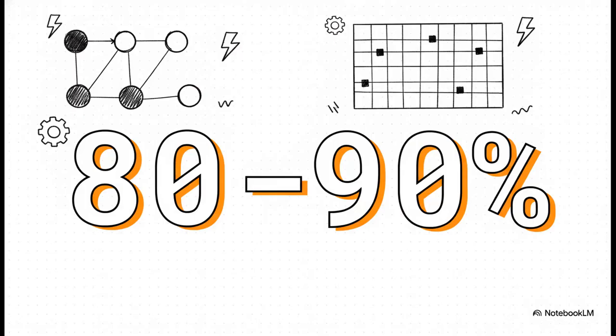Now, what's really interesting about this is a very specific number, 80 to 90%. See, because each bus typically only connects to a handful of neighbors, maybe 2 or 3 lines out of a massive system of thousands, the vast majority of the entries in our Ybus matrix are just zeros. This massive sparsity of 80 to 90% zeros is the actual magic trick. It's what makes solving networks with tens of thousands of buses computationally realistic on a computer instead of totally impossible.